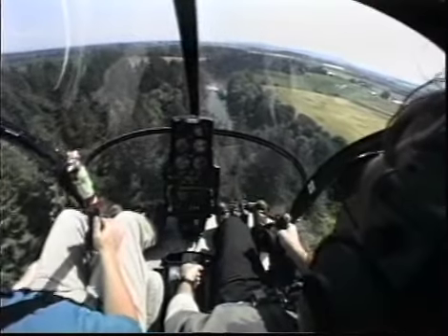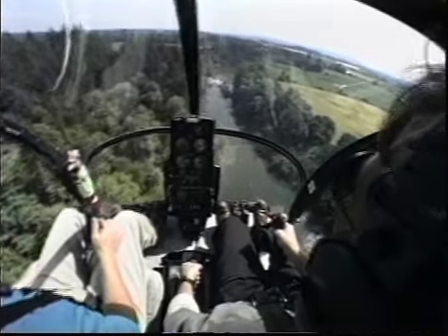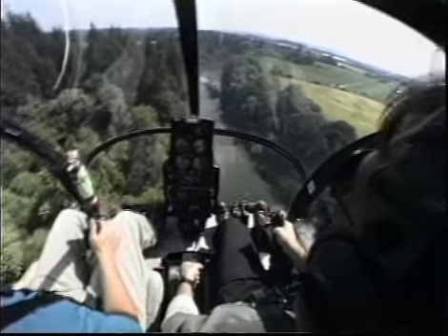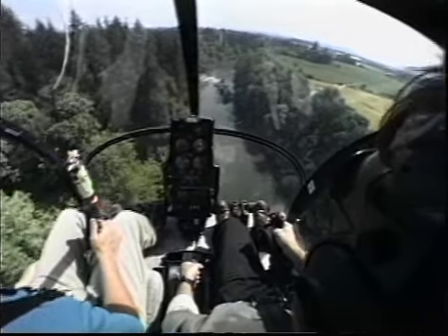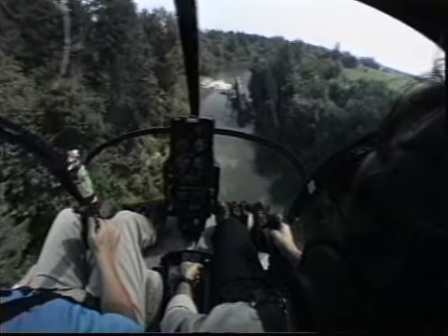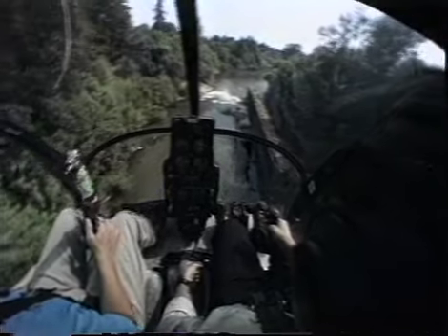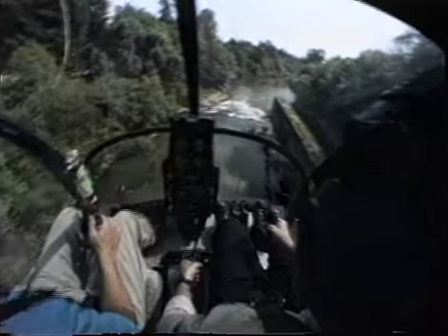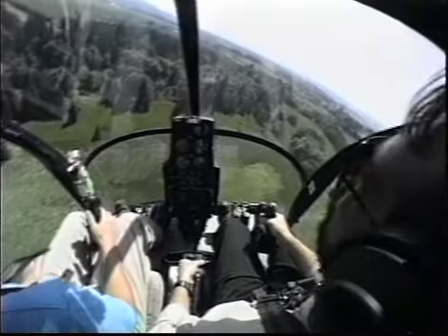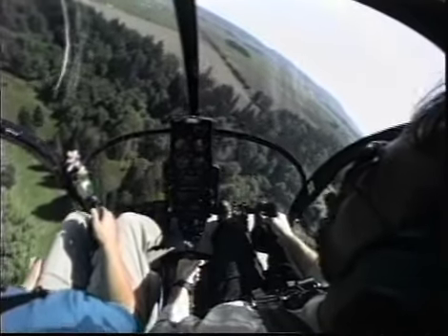If flying only involved traveling from airport to airport, all we'd really need would be airplanes. However, the unique capabilities of rotorcraft permit us to take off and land in all sorts of places: city centers, mountain clearings, parking lots. To operate safely among buildings, trees, power lines, and so on, the pilot typically follows a confined area procedure. A confined area is defined as any area where flight is limited by obstructions in one or more directions. First, perform a high reconnaissance to determine the suitability of the area for landing.